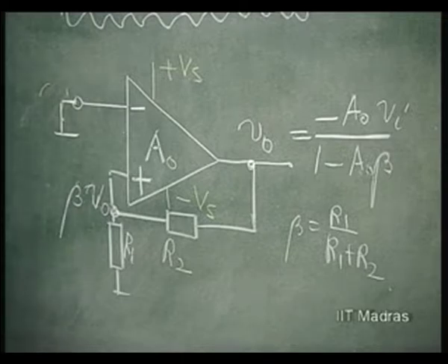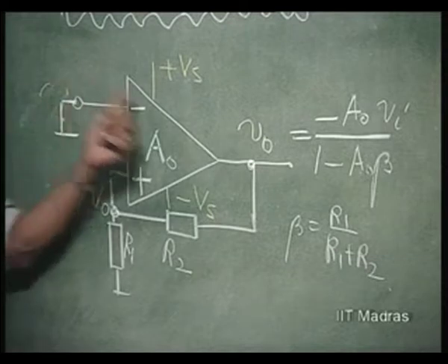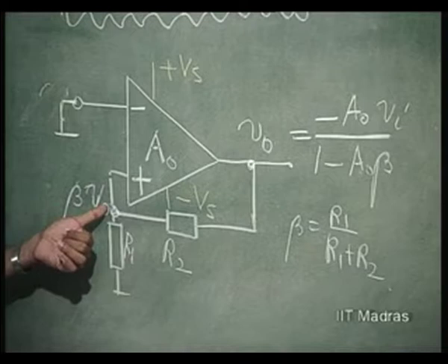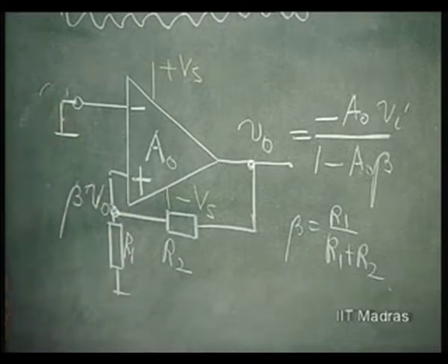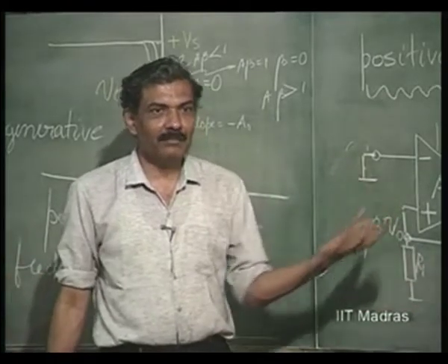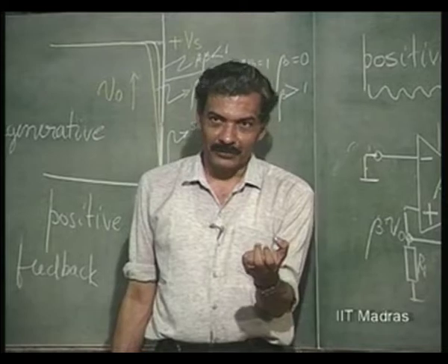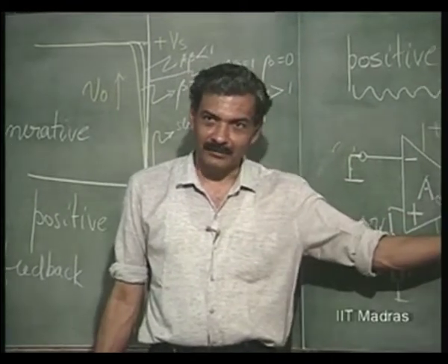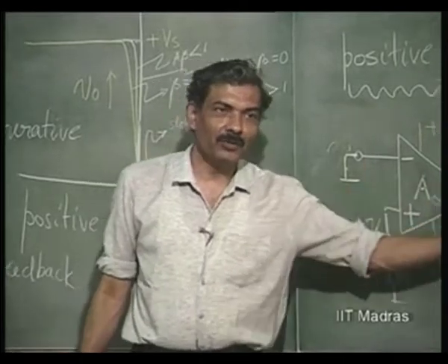If A beta is less than 1, you will see that all these feedback voltages should be simultaneously existing, which means with A beta less than 1, the series which is 1 plus A beta, plus A beta squared, etc., will become a stable output. As long as the input is there, output will be stable at a certain value. The moment input is removed, output will go off.